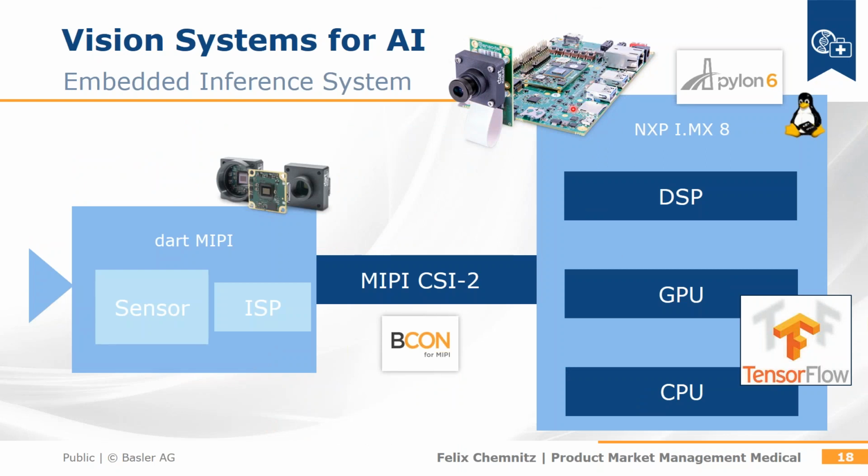I would say this is an outline of 10 by around 12 millimeters, but this is the evaluation board itself. So you can go much smaller in size if you do a custom design. There are abilities to shrink that down, because here are all the breakouts: USB 3, GigE, HDMI, a slot for an SD card. If you don't need these, you can get rid of them in your own custom design, so you can shrink that down by far.